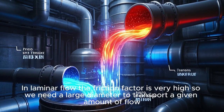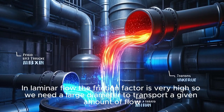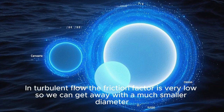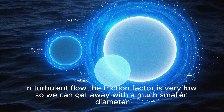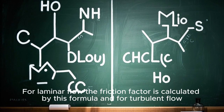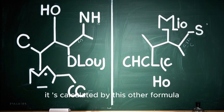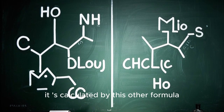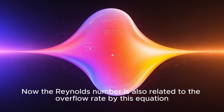In laminar flow, the friction factor is very high, so we need a large diameter to transport a given amount of flow. In turbulent flow, the friction factor is very low, so we can get away with a much smaller diameter. For laminar flow, the friction factor is calculated by this formula, and for turbulent flow, it's calculated by this other formula.